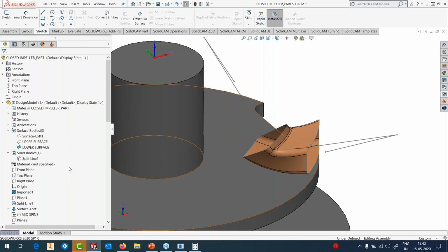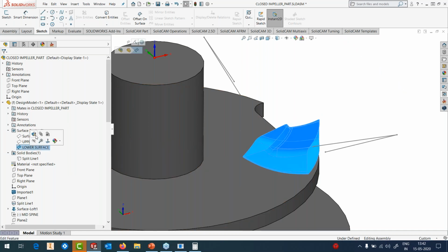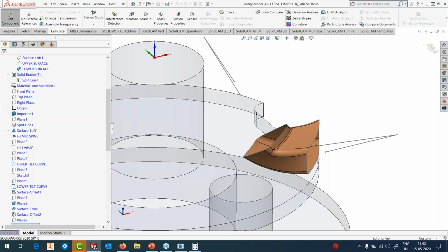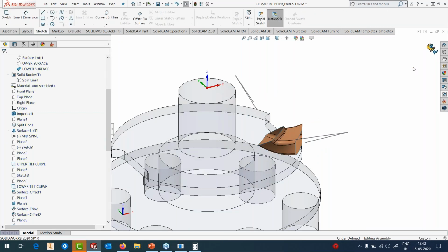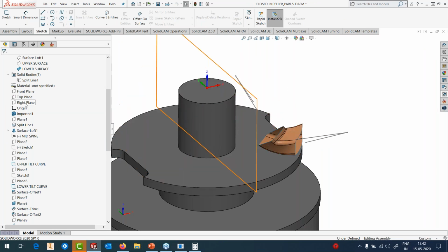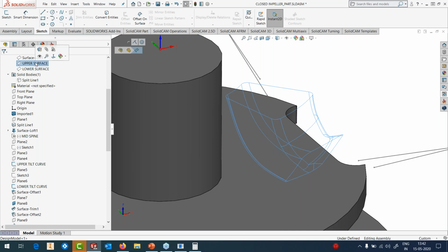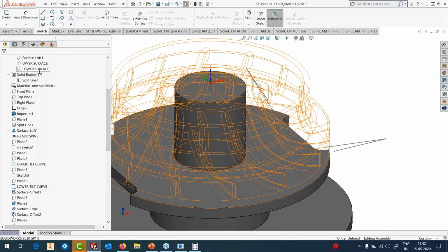I'm going to machine it in a different direction. And then I have created another toolpath which basically overlaps between these 2 toolpaths, one coming from the top, one coming from the side. It just overlaps to make sure that there are no mismatch marks between these 2 toolpaths. So this is all I've done with this particular part. But like I said, this entire exercise of creating this is approximately 2 hours. So I can't spend 2 hours today because we have to cover a lot of things. So what I have here is the upper surface.